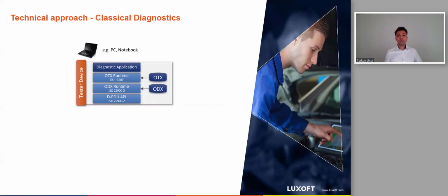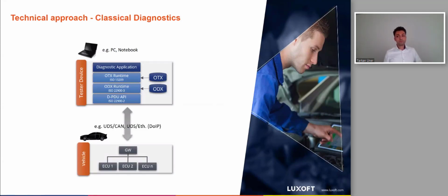The automotive industry faced this problem quite some time ago, and standards were defined, a couple of them, meanwhile, as an ISO standard. Test sequences, test logic can use ISO 13209, also called OTX. OTX means Open Test Sequence Exchange, a standard to create test sequences in an exchange way. Communication, bits and bytes versus human readable form are defined in ISO 22900-3, also known as ODX, Open Data Exchange. Putting bits and bytes together, adding all necessary additional information to it so that the message can be sent over a bus system is defined in ISO 22900-2. All these pieces in combination represents a diagnostic tester.